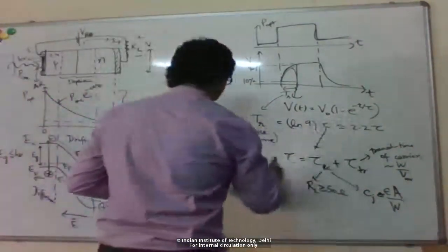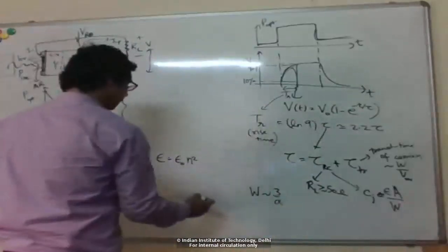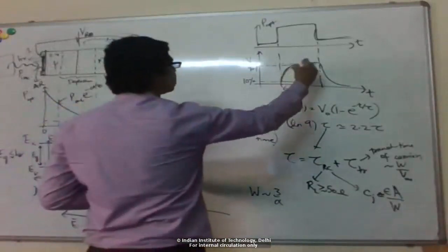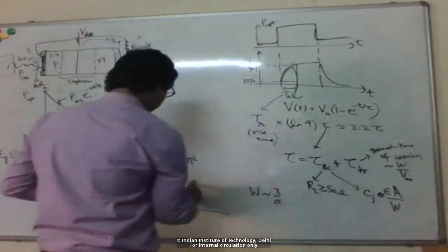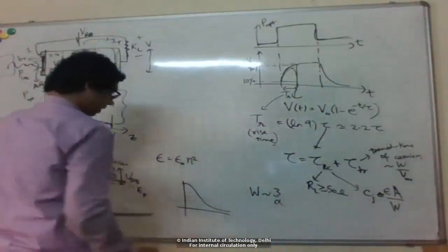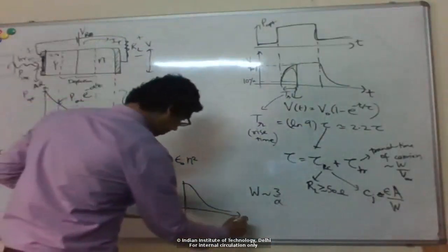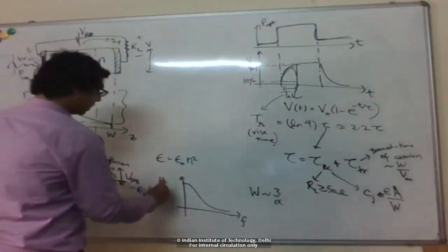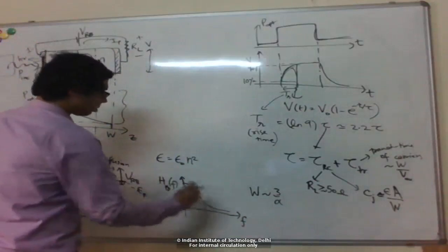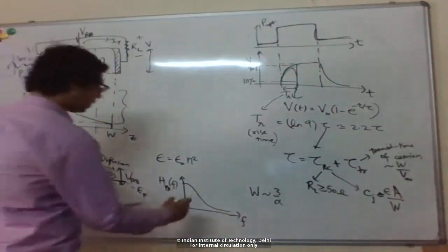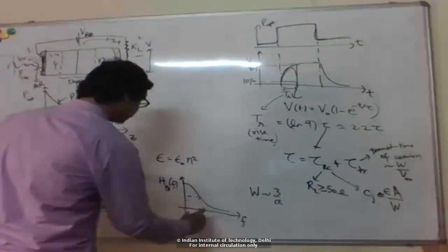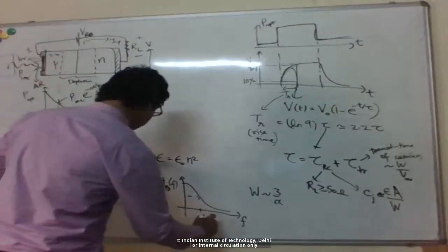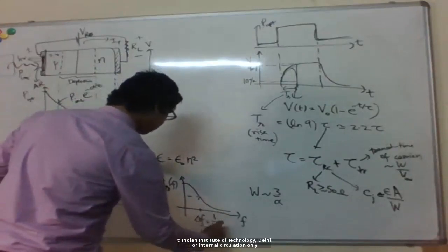Right, so equivalently, I can think of this in the frequency domain. If I take the Fourier transform of this exponential function, I get a low-pass filter kind of response in frequency. So if I look at the photodetector frequency response, it looks like a low-pass filter. Again, if I look at the bandwidth here, delta F looks like 1 over 2 pi tau.